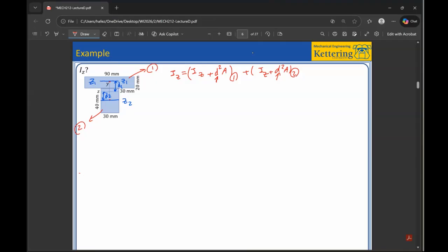So to do this, we have to resort to what we learned in statics. So centroid calculation. We really want to know where the z-axis is residing. So C, let's call it the overall centroid. So we learned in statics, the first item is pick coordinate system.